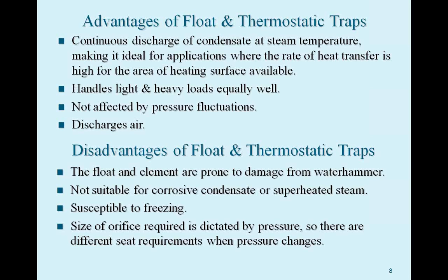Disadvantages of float thermostatics. The float in particular can be prone to damage from water hammer. If a slug of water gets sent in there and hits that hard, it can damage the float, crack it, dent it, that type of thing. Not real suitable for corrosive condensate or superheated steam. We've seen applications where the ball will come back and it's been corroded, eaten away because of acidic elements within the condensate itself. It'll eat that ball and you get a little crack in there, and obviously then the ball will fill with liquid and won't lift anymore.